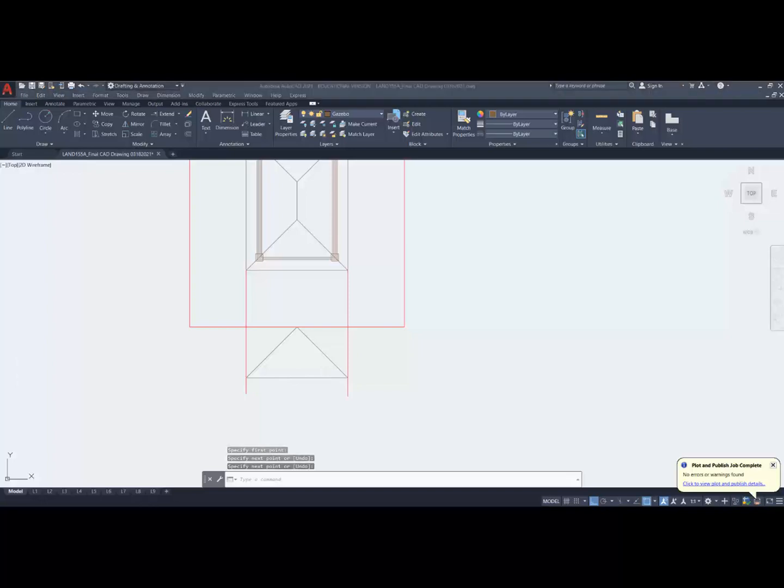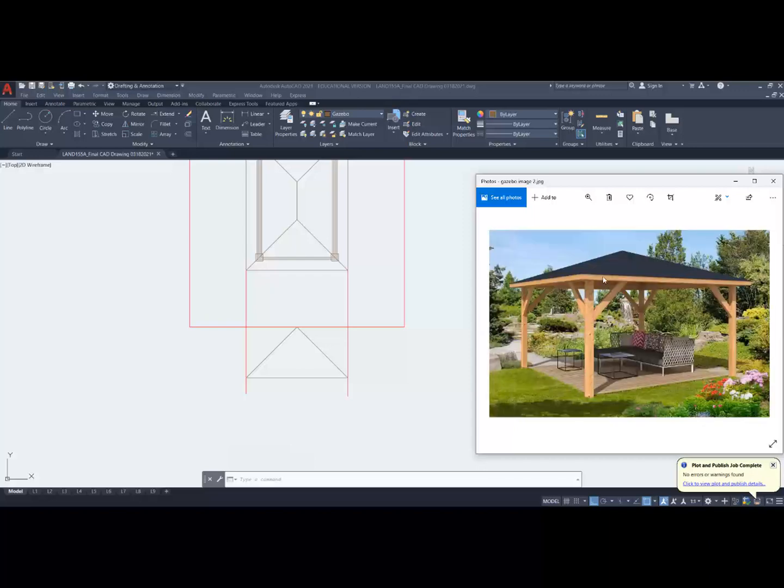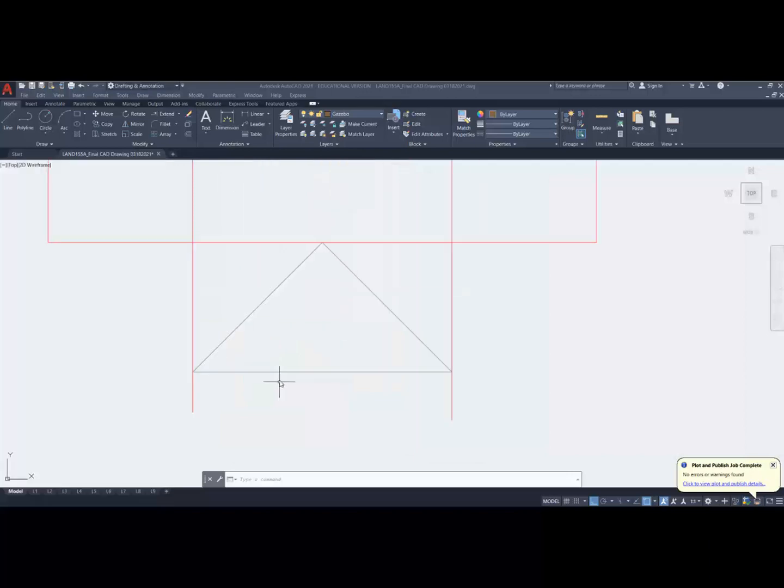So remember, in this particular example, there was no fascia board here. The fascia board is a covering, so we don't see the ends of the joists. All right, so how big is a fascia board? It could be either a 6 or an 8-inch. I'm going to use a 6-inch for now because of the scale of this. So a 6-inch board is only 5.5 inches in width, so I'll offset that 5.5. Select offset 5.5.